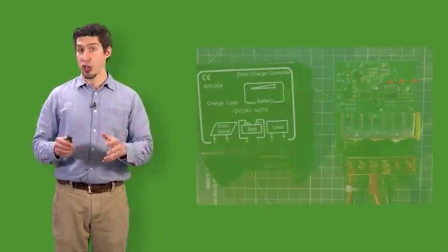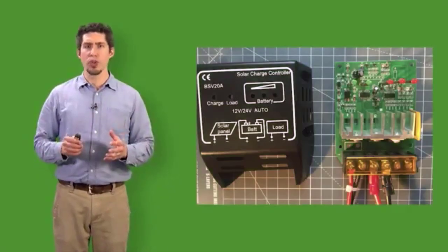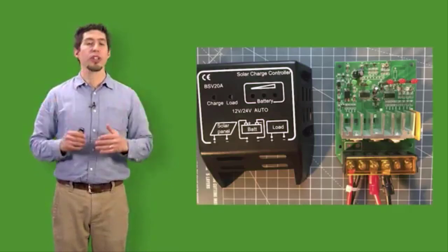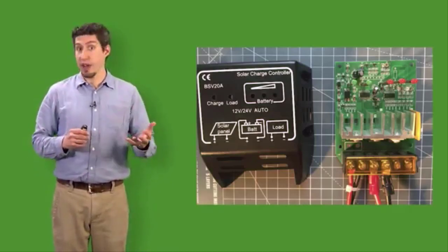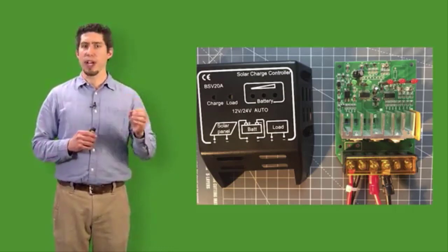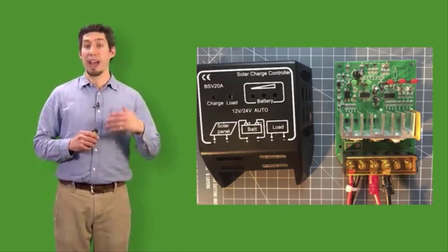The one other piece that's needed with a battery system is a charge controller. The charge controller ensures that batteries are not undercharged or overcharged to prevent the risk of failure and/or fire. So the charge controller is an important piece and the brains of the operation between when the battery gets charged or discharged.